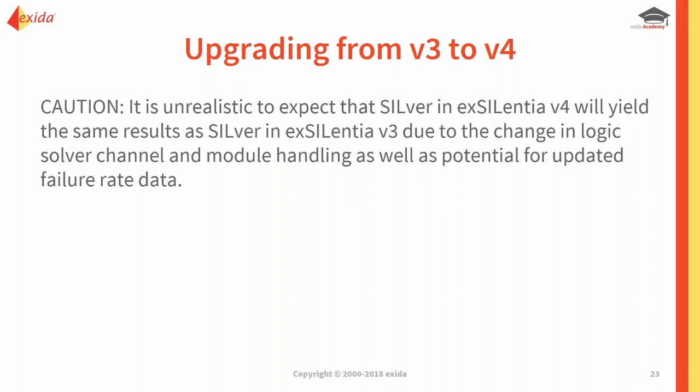Now, having said that, we're talking about a very, very small difference. We're talking 1, 2, 3% maybe difference, if at all. The logic solvers tend to be negligible from a probability of failure on demand perspective, at least in the typical safety function. So the fact that we've moved some things around there, that the I/O channels are handled differently, is not going to be that big of an impact on your overall calculated probability of failure on demand. And we've run thousands and thousands of calculations where we looked at the results, and it is in that 1-2% range, if at all.